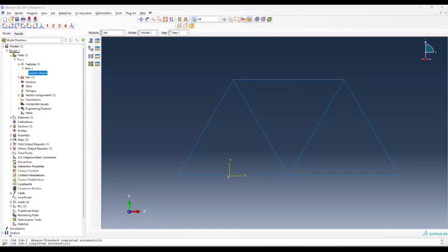Why is global size 50? No, okay, so Ethan, I think I answered that, but if it's not clear, let me know. Said, could we initialize the truss without any boundary conditions and add the fixed roller in the later step? I was just curious why you need to. Yeah, you could. I think you could do it that way. I don't think it would really make a difference. I think though for correctness at least, especially when you do 3D problems where you need all degrees of freedom to be restricted, it's best to use that encastre boundary condition so you can fix it in all directions. Does that make sense, Jimmy?